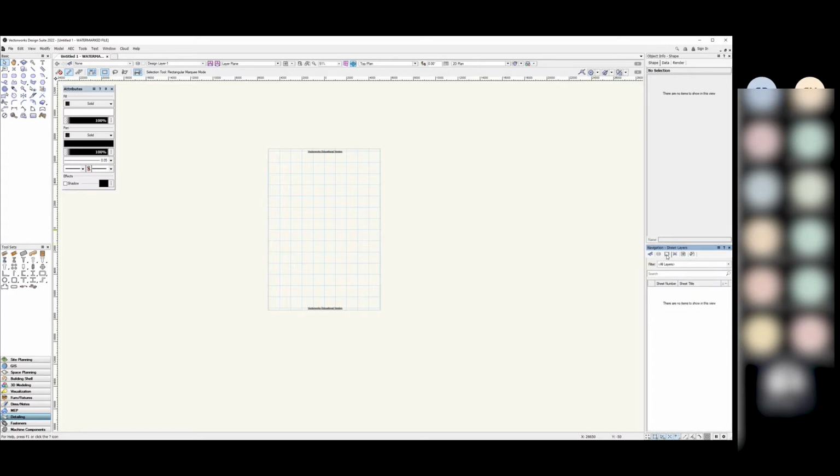The third tab is sheet layers. Sheet layers are essentially, if you're looking to print out your drawing, you can basically tell your drawing to go onto your sheet at a specified scale. Actually, no, that's not quite true. It's a kind of combination between sheets and viewports. So the sheet is just setting up the page size. So for instance, I could configure this to be A3 landscape as an example. And then it's the viewports where I can tell the drawing from the design layer to go onto that sheet layer. That's a better way to explain it.